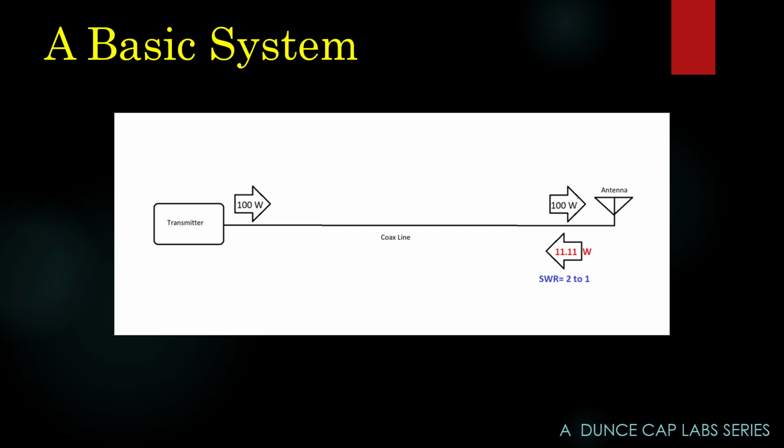Also, this transmitter is at a very busy tower site, and there are antennas very close to this one. So there might be a little energy coming down my antenna line back toward my transmitter that came from some of those other transmitters. When those signals and my reflected power and my forward power all mix in my transmitter, I'm going to get intermod mixes, which will generate terrible interference. So I don't want that.